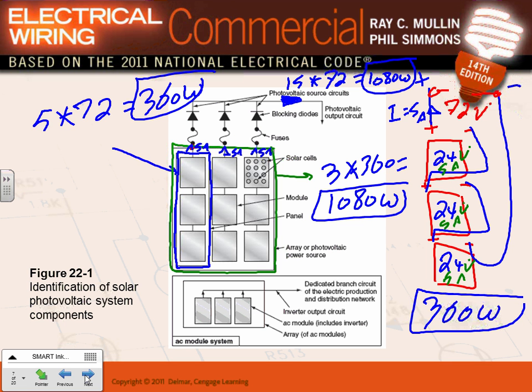One more time. When you put the panels in series, the voltage will add up. The current stays the same. The watts for the system is the amps multiplied by the voltage, which gives you 360. So basically, that's how much power you can get out of this plant.